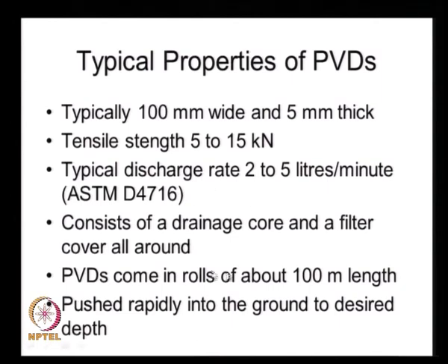And as I already mentioned, these PVDs consist of a drainage core and a filter cover all around, and the main advantage of these PVDs is they come in large roll lengths of about 100 meters or more, and these can be pushed rapidly into the ground to desired depth, because that is where the major difference between the sand drains and the PVDs comes in.